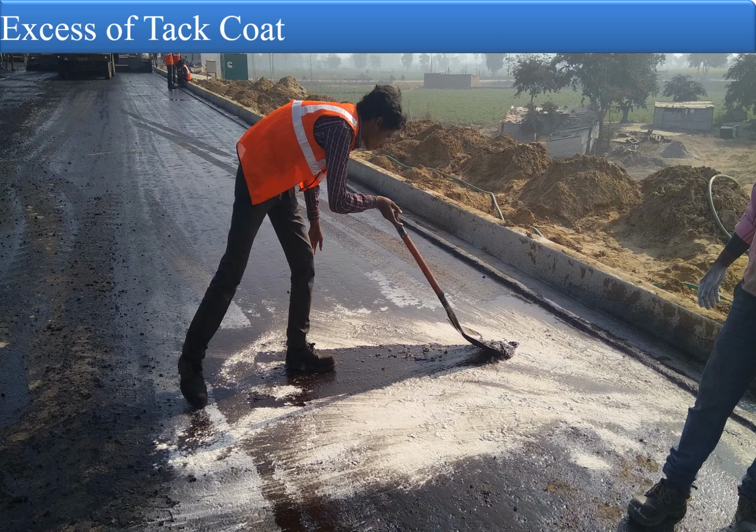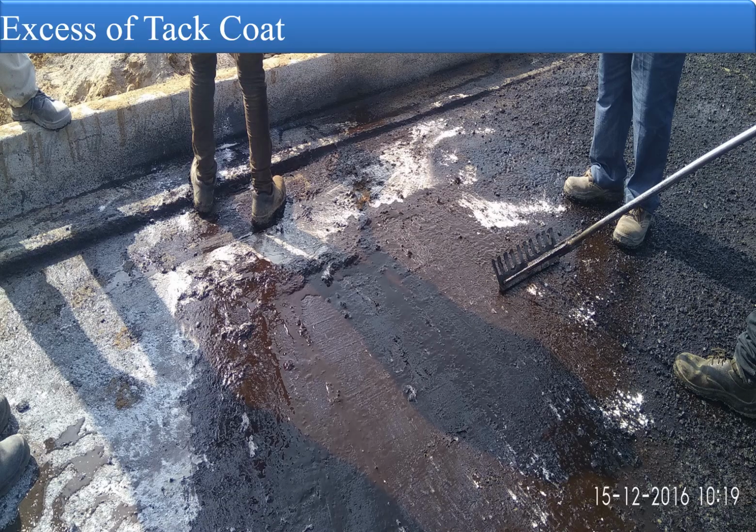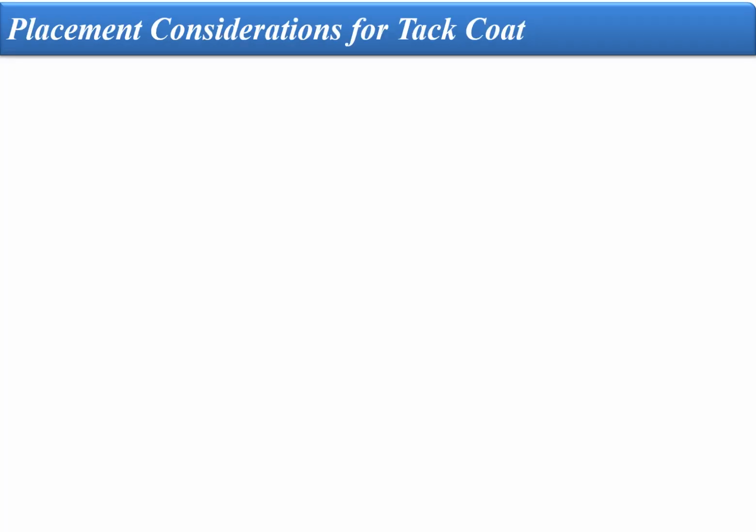You can use tools to remove the material which is mixed with lime and emulsion. So this is how you can clean up the area finally, brushing it cleanly and neatly. Once that cleaning is done, you can run the paver to pave the next bituminous layer. It can be any layer, maybe a DBM second layer or the BC, which is the final layer in any